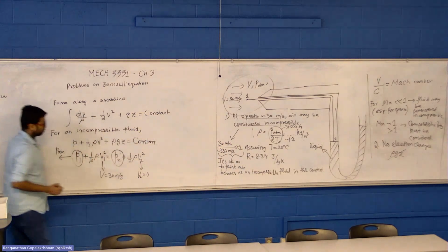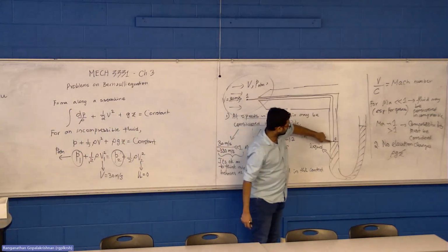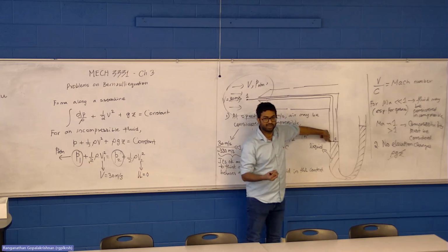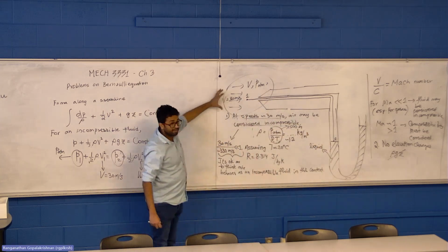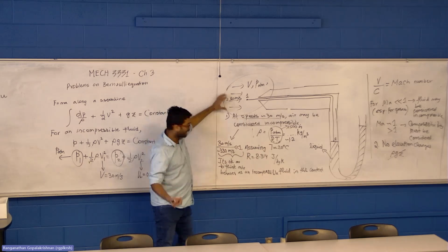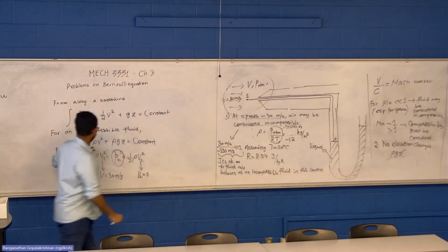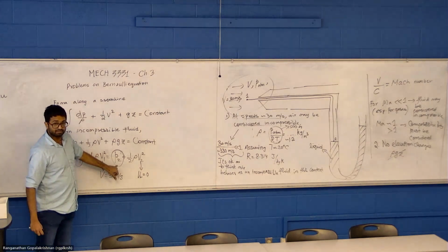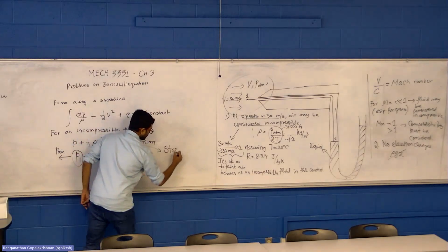And P2, okay, P2 is the pressure exerted by the fluid when all its bulk motion has been converted to thermal motion. That is, all the kinetic energy with which it came inside has been brought to rest and it is now only undergoing thermal or molecular motion. So all the pressure that was previously related to the motion, which is the half rho v squared, is now within this pressure. And this is what I talked about in the previous lecture. This is the stagnation pressure.